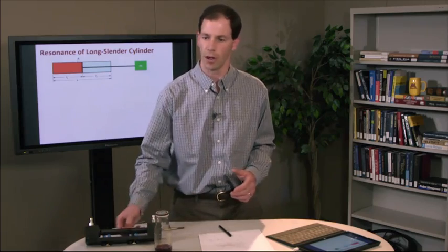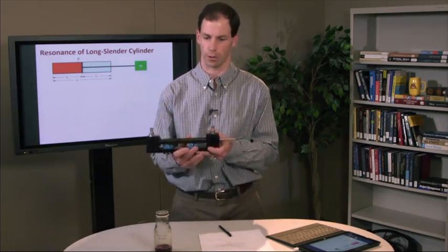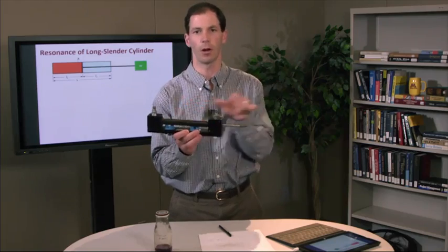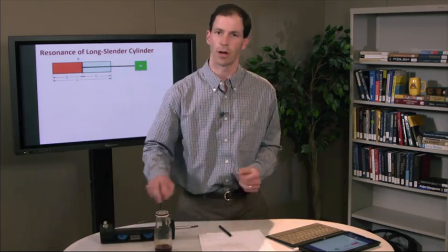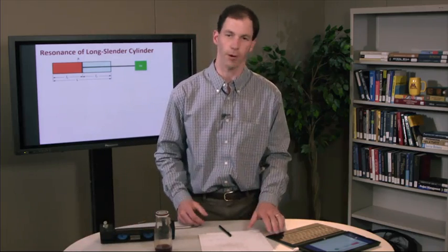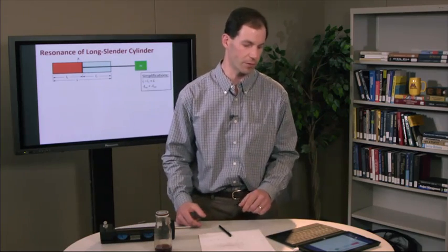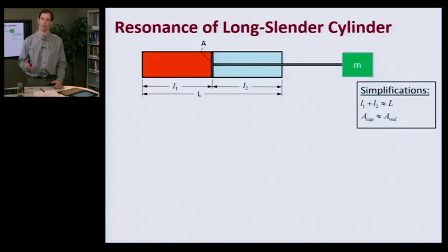So let me talk a little bit more about resonance as one of the key areas where this becomes important. Think about a long, slender cylinder, something like this, relatively small diameter, long stroke. I'm going to do an analysis of what the resonance frequency, or the natural frequency, of this system is. I'm going to simplify this ever so slightly,